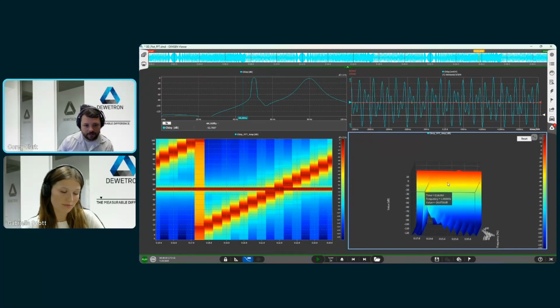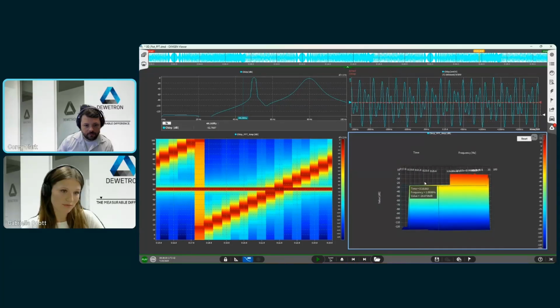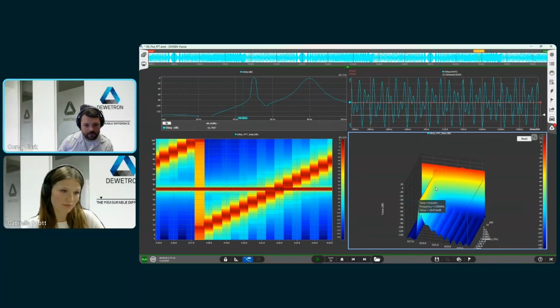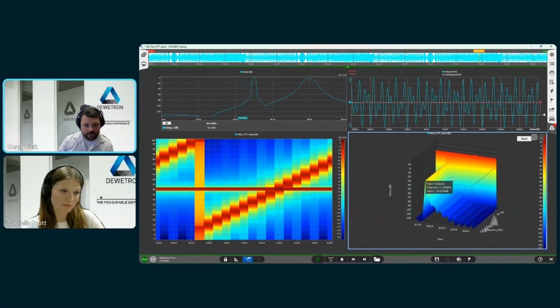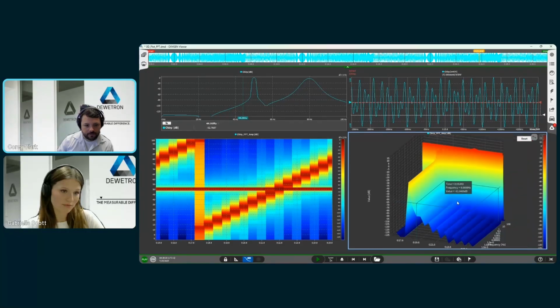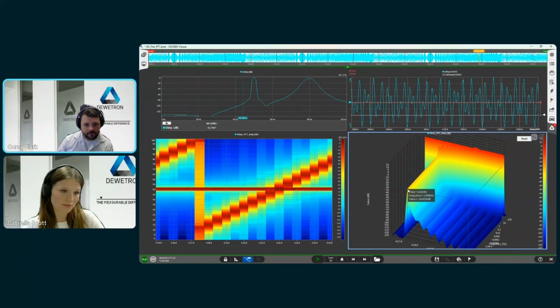On this 3D plot instrument, we can right-click and move around to visualize the data and rotate the instrument as we see fit. We can left-click and move the instrument around as well. And then you can, of course, scroll up and scroll down to zoom in on this instrument. You also have the ability to click within this instrument to set the cursor position and then get a readout of the values that are actually at the position itself.